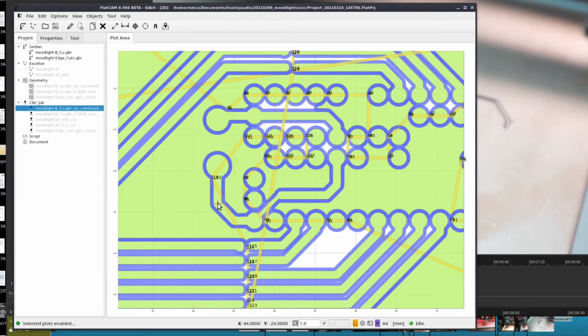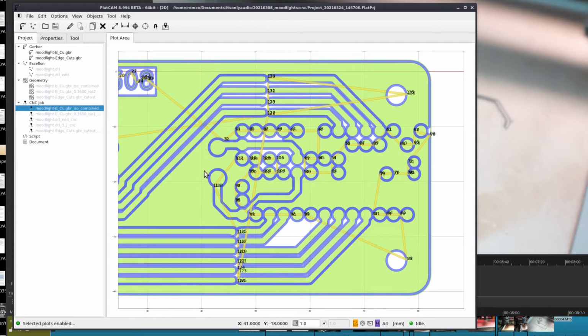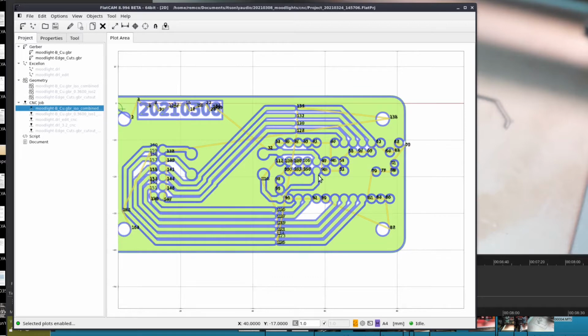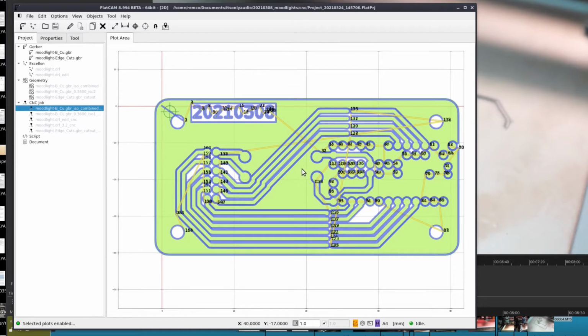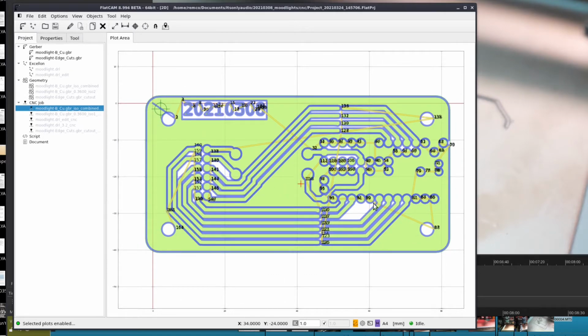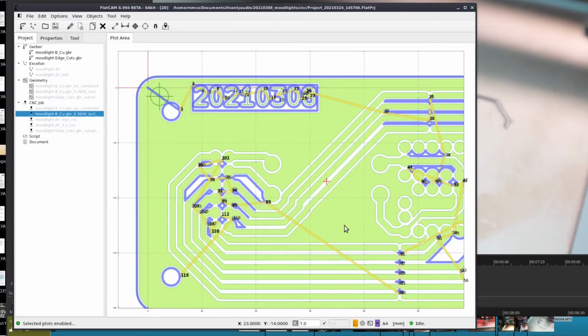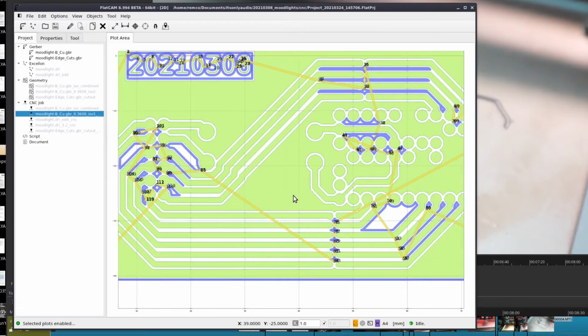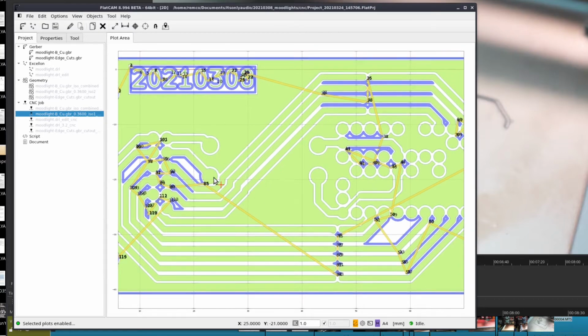And I start to think that doing CNC routing actually makes you a nicer circuit board designer, in the sense that you start to generate designs that are easier to fabricate, and even if you send them to a board house, the board house will be grateful. I also made a CNC file for a second pass. Should the first pass not yield enough isolation, this file only does the second pass, carving out space between these tracks and these little islands here. We only will use this if necessary.